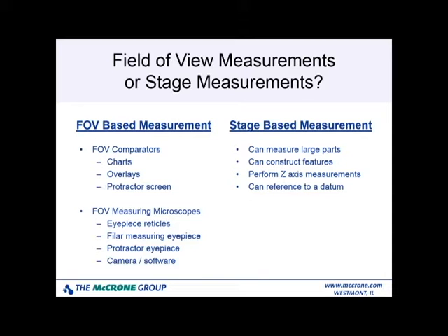And of course, you can mount a camera or software. But on a stage measuring system, you can measure larger parts, parts that are larger than the field of view. You can construct features or relate features that you've measured to each other. You can perform z-axis height measurements, and you can relate the features that you measure to a datum.